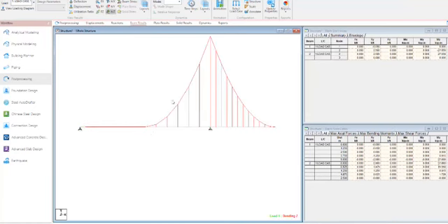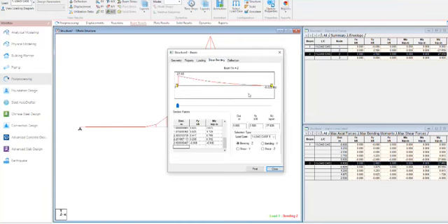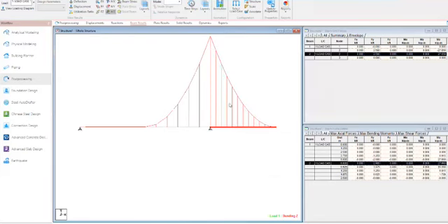So in beam results, if you see here, this moment becomes 0 here. So this is hogging moment. Values also, if you see it here, the value of the moment is 2.5 should come, right? So it's like a uniformly distributed load. So the equivalent distance is here. Then the bending moment is 27.659 as the maximum, because here it's a uniformly distributed load.